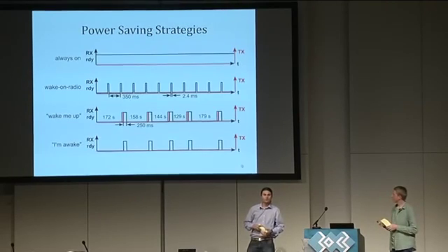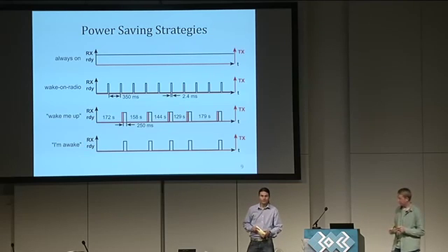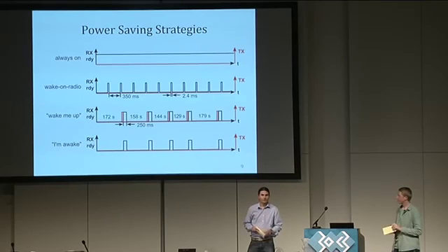The receive ready mode draws about 14 milliamperes of current, so that the battery would be empty in about 1 week. So if you use a wake on radio mode, the average current draw is reduced to about 100 microamps. And the other modes reduce the current draw to about 20 microamps, plus additionally the current draw of the motor and the microcontroller, so that the batteries can last 1 year or even longer.